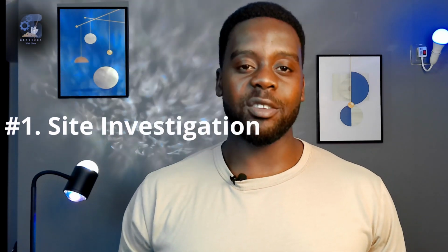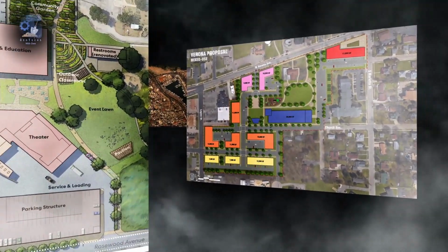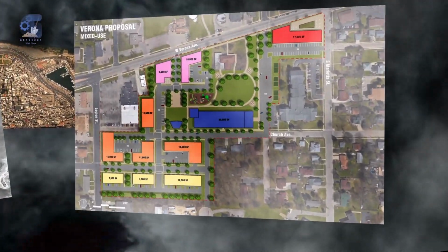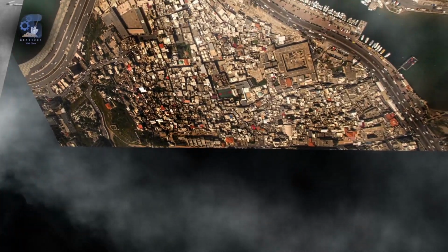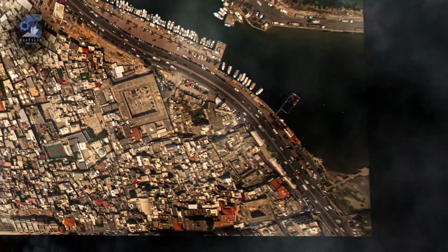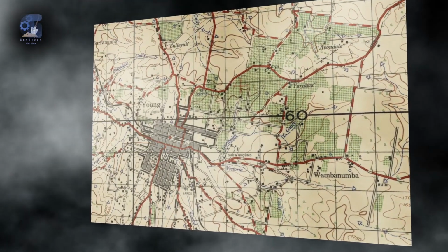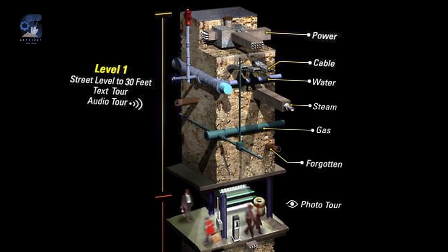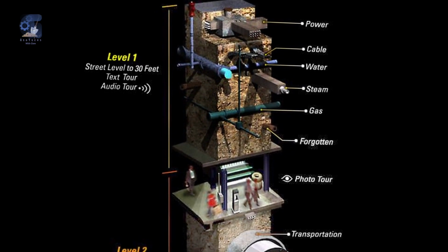This brings us to the aspects of foundation design and construction. The study of the site history is a good place to start. The information on the site history can be obtained from various sources, including plans of previous and existing developments, some aerial photographs, old topographic maps, together with geological maps and memos. This is important because useful information on the possible presence of old foundations, abandoned wells, and tunnels may be extracted from a study of the site history.